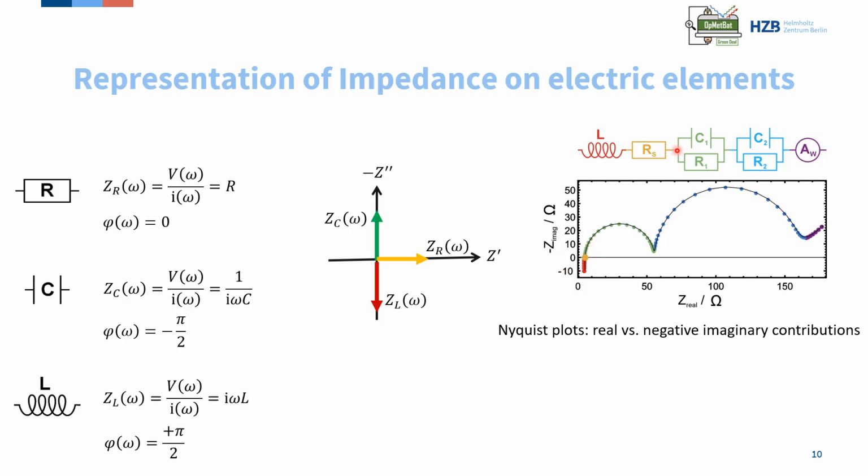Next are the RC units, which consist of a capacitor and a resistor arranged in parallel connection. This is related to charge transfer processes, and with some modification can be seen as semicircles. Additionally, the Warburg contribution represents the diffusion and appears as a final tail with a certain slope.